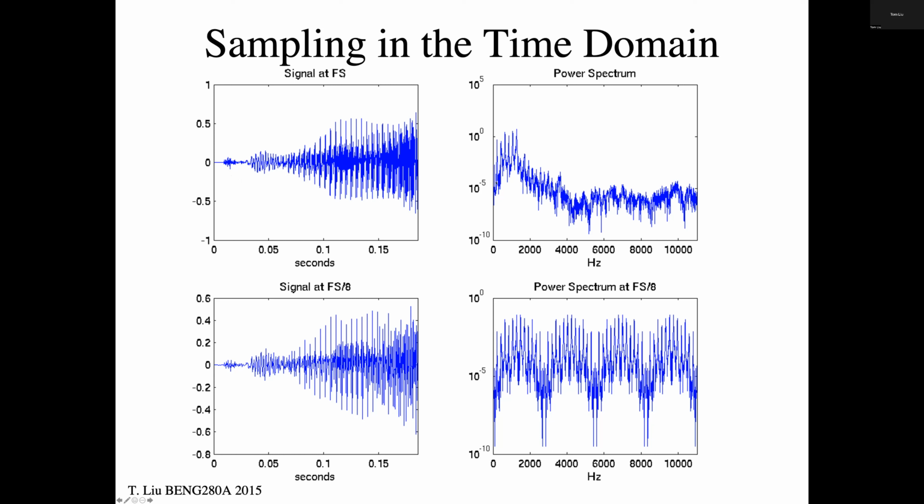right? And when we take the Fourier transform, we can see here's our frequency in hertz that is represented inside this signal, and this is the relative amplitude or power spectrum at a particular frequency. That's when I'm sampling at this rate. Now let's take every 8th sample. Say I have a receiver where sampling this high was too expensive, so I got a cheaper receiver and it can only sample this fast, in the radio frequency realm. So I'm going to get a sample at every 8th point.